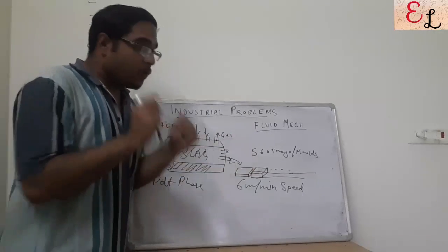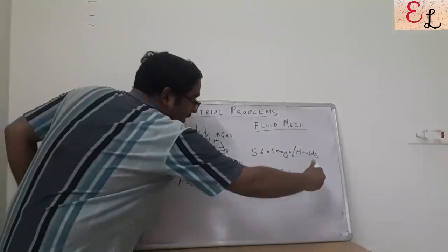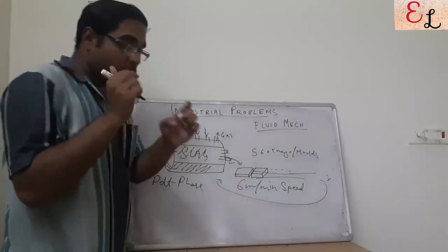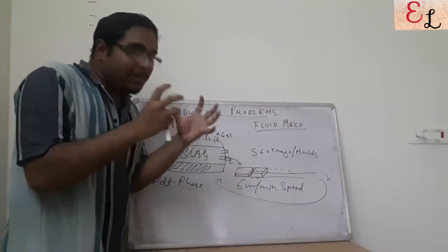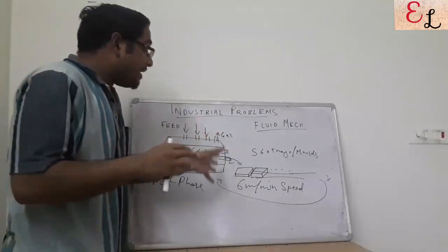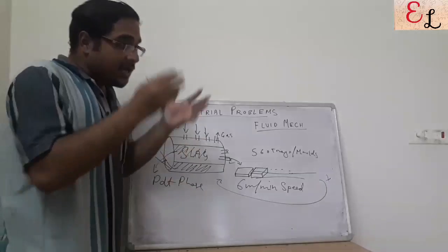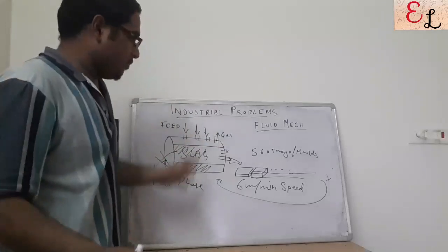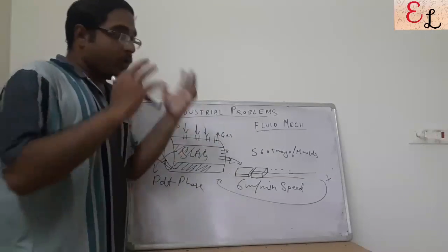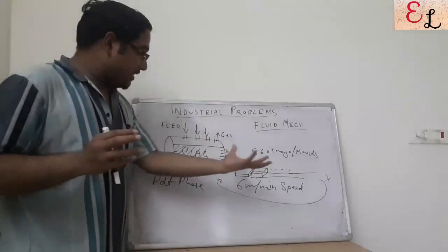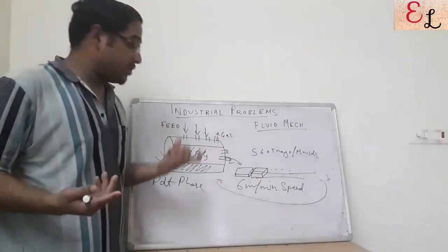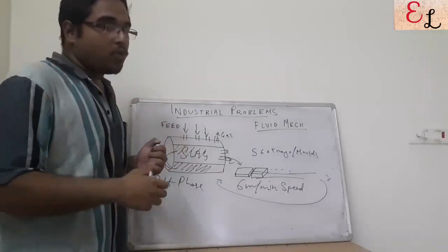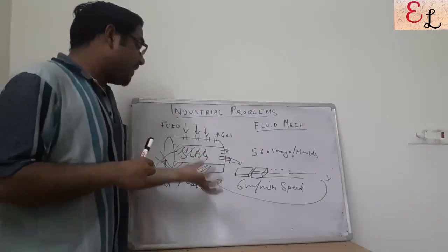Primarily this is one of the reasons. Another reason was the metal getting stuck on the molds. On the return stroke, when it is getting filled up again, the metal was not completely removed. Some amount of metal was sticking to the surface of the molds, so since it is now of lesser volume, it would overflow. But neglecting that problem for the moment, the high flow rate due to the increased feed means the molds and the rail speed are not able to tackle the situation. To change the speed, the motor and the entire railway structure is a difficult and tedious task.